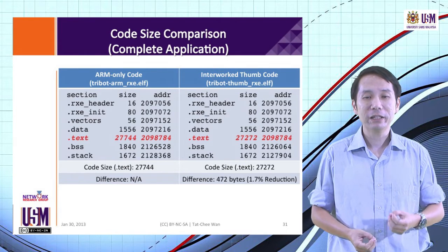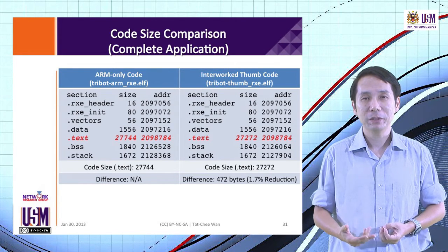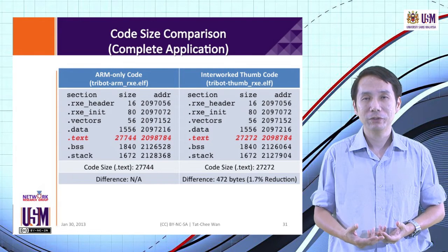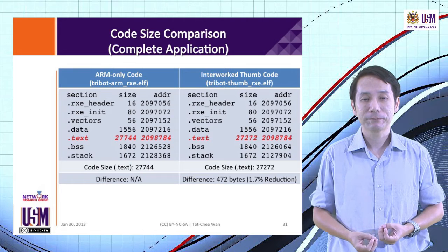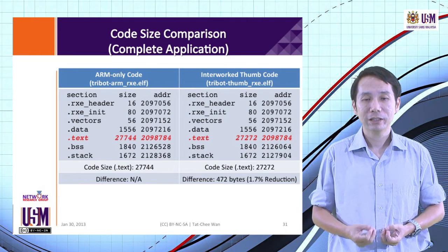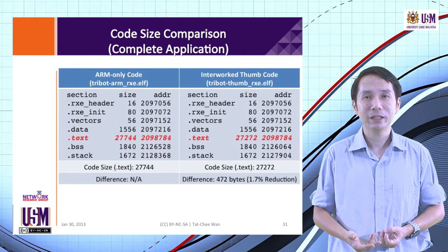Finally, large value constants such as the address of variables need to be accessible within a reduced instruction offset range, because the Thumb instructions have a limited offset range for retrieving literal constants. To achieve this, we will need to use the .ltorg directive and place it somewhere within our source file where it is needed. Otherwise, the assembler will generate errors where the offset exceeds the range allowable for Thumb instructions.